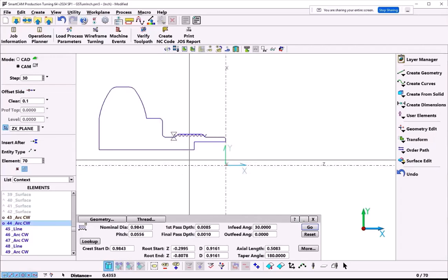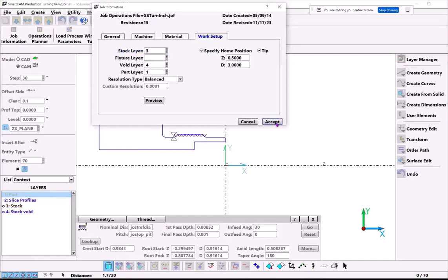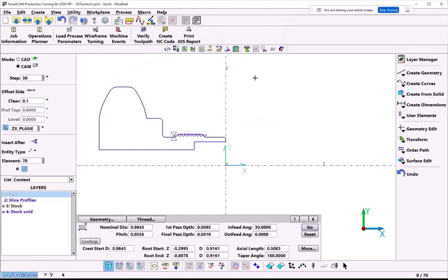So now we're going to switch to the ID. Remember the home point, 1/2 inch and 3 inch, is always up here somewhere. Okay, so our thread tool finishes up here. And the next thing we're going to do, we're going to drill the hole through here with a ream. And right now our tool is stationed up here. So when we go to our drill, that's going to be fine because it's going to go from here down to here and it's not going to bang into the part anywhere. So we can go ahead and drill this.